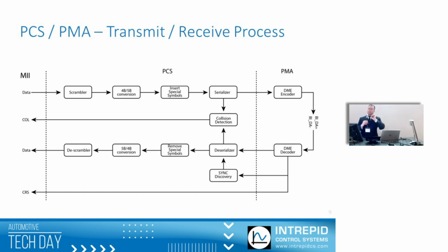So this is a unique scenario for modern Ethernet. Modern Ethernet, anything in the last 20 years, you have full bandwidth in both directions. That means, I don't care what node you are, you can transmit anytime you want, and you're going to get a full bandwidth network available to transmit at any time you want. So that's different than 10BASE-T1S. Now we got multiple transmitters on the same two wires. You cannot transmit at the same time on the same two wires.